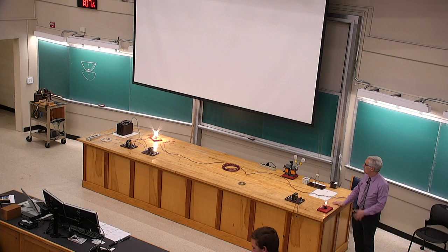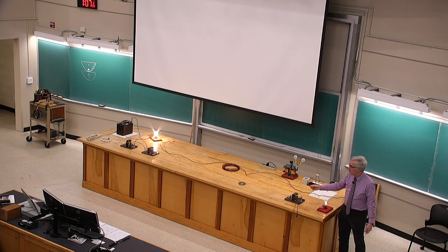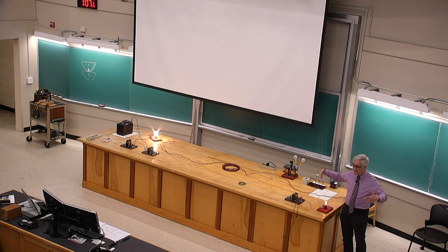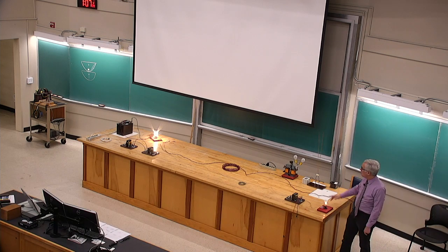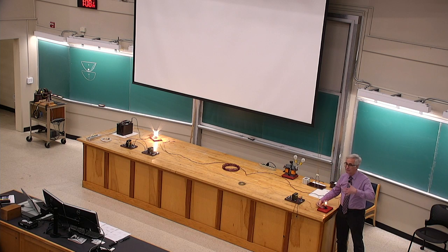What's the problem? The problem is that wire now, which is quite long, and in this case we chose it deliberately to be relatively thin, more like speaker wire than electric power carrying wire. It's got a high electrical resistance now because of its length and because of its thinness. It charges a big fee to carry electric current, and so while the voltage at the positive terminal of the battery is 12 volts, the voltage at the other end of that positive wire is not 12 volts anymore. It might be only 8 volts.